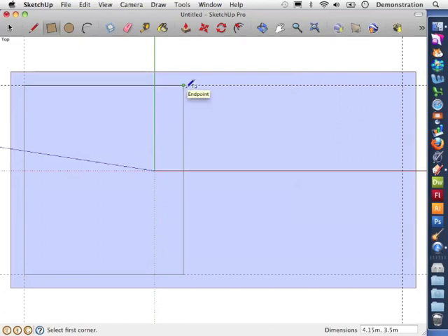I'm now going to add the thickness for my wall, which is 15 centimeters or 0.15 meters. So again, I need to use my tape measure tool to measure that distance. Now the tape measure will still be remembering the 0.3 from earlier. So I'm just going to drag out any distance and click, and once again I'm going to go down to the bottom right and set the exact length I want it to be, 0.15 meters. And you can see it's altered where the guideline was drawn.